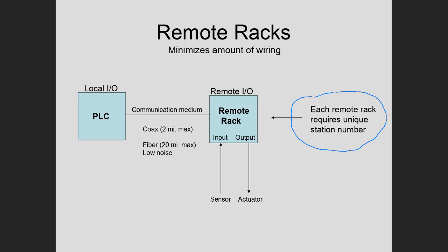Well, here's where PLCs were different. With the PLC, you can actually address individual bits. And we'll talk about the importance of that as we go along. So that's one big thing to know.